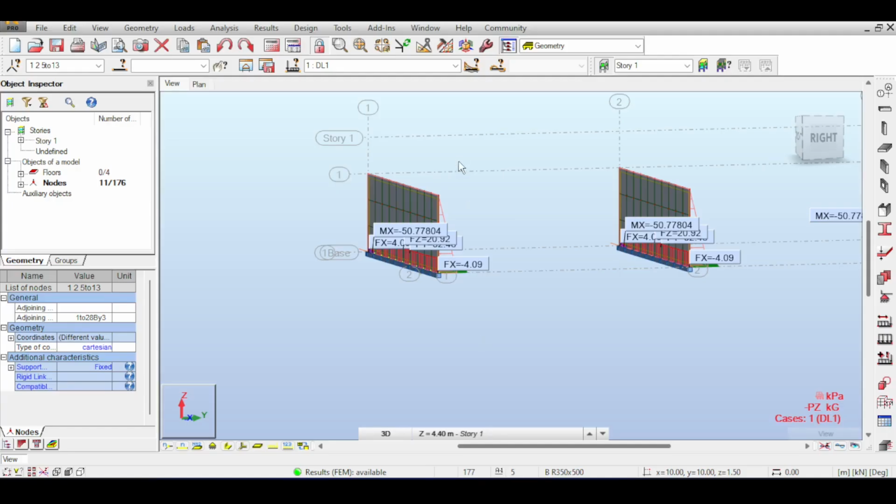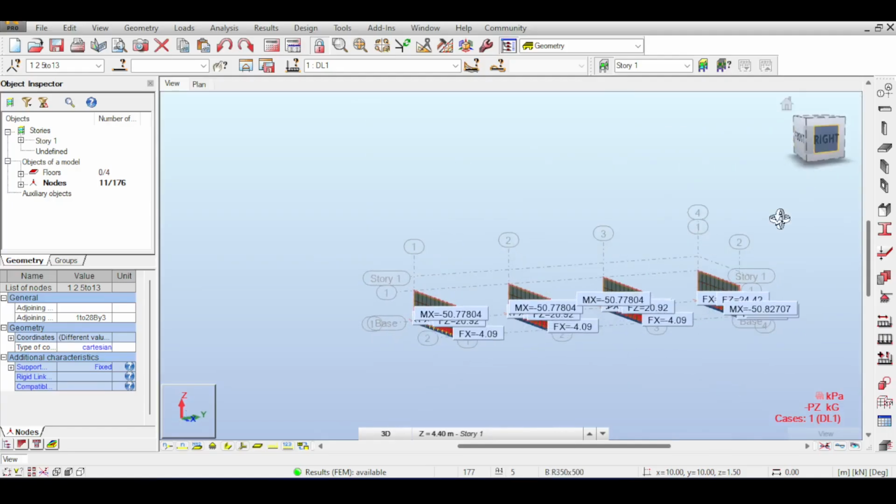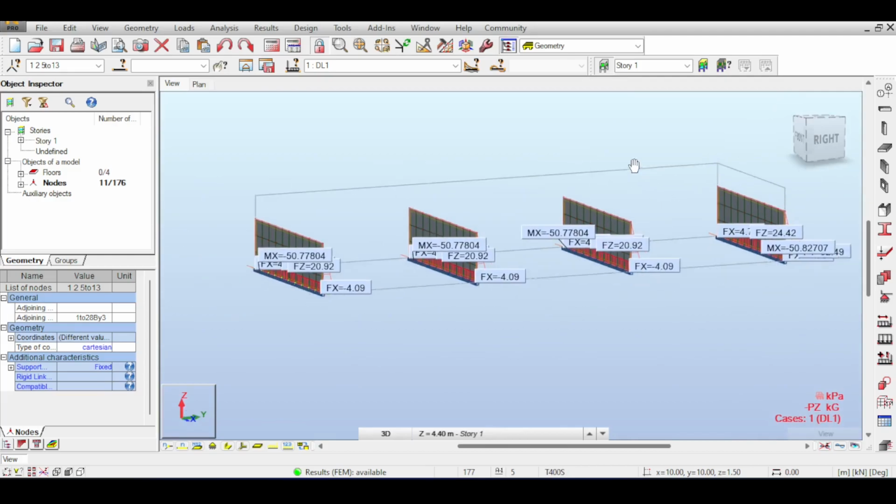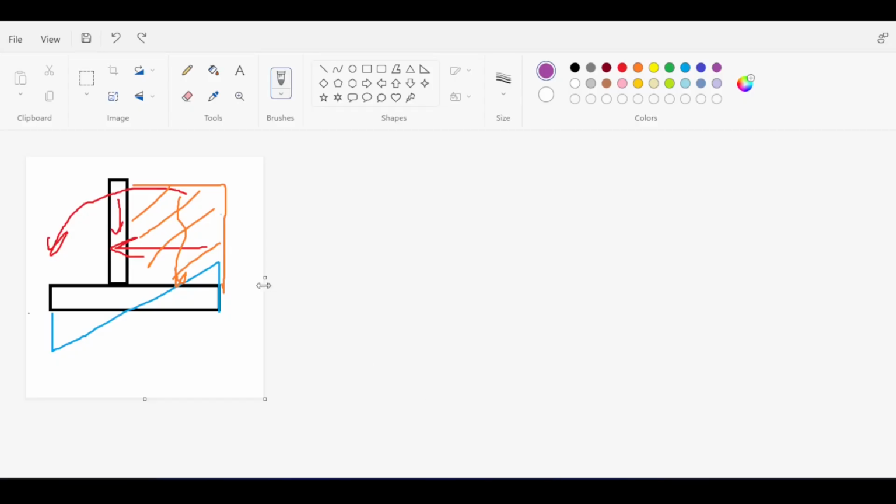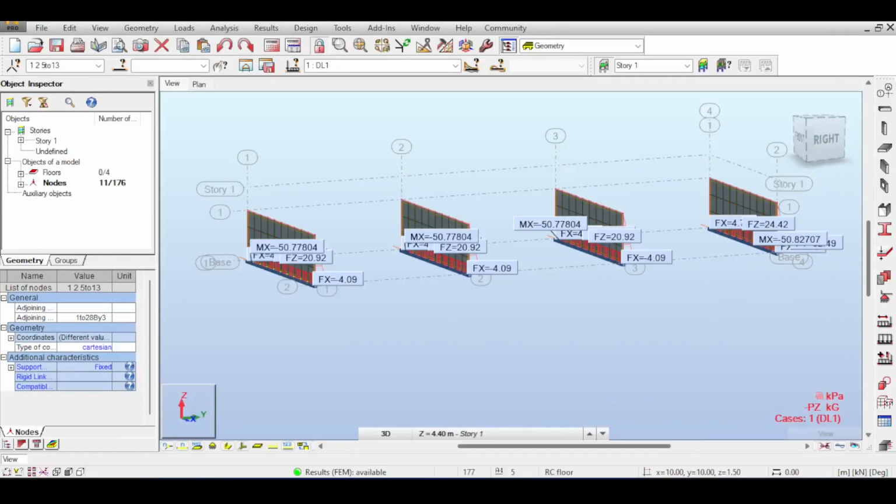I just wanted to mention that this is one of the options that are available, but that should be your last option. The problem with Autodesk Robot is that there is no single retaining wall module, which means that those intricacies are things that you have to keep in mind yourself, and you will have to basically take them into account yourself. Now, my plan for those 4 retaining walls is as follows. The first retaining wall is basically a retaining wall where I will let Autodesk Robot decide the distances and dimensions of the retaining wall himself.